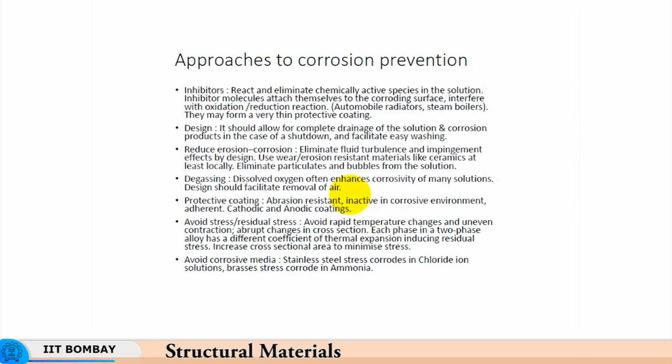So, let us say the workpiece gets heated to a certain temperature above room temperature during work, then these will expand to different extents, inducing stresses in the material, and these stresses will result from differential thermal expansion. The stress distribution in the metal will change over a period of time, and therefore, the tendency to get corroded will also keep on changing.